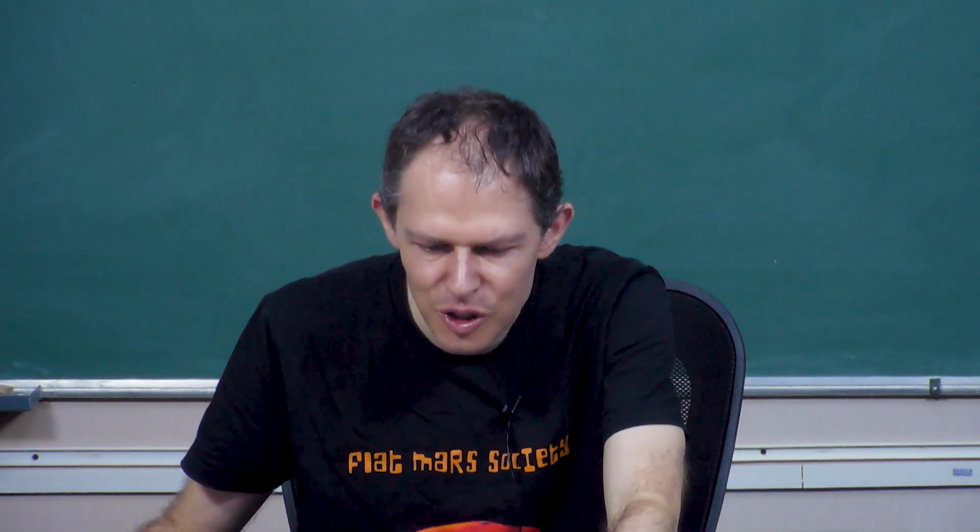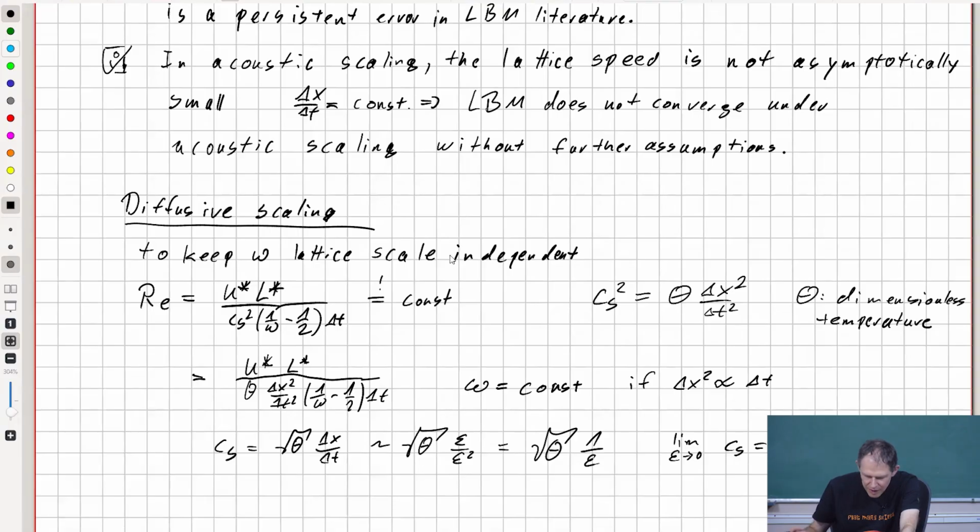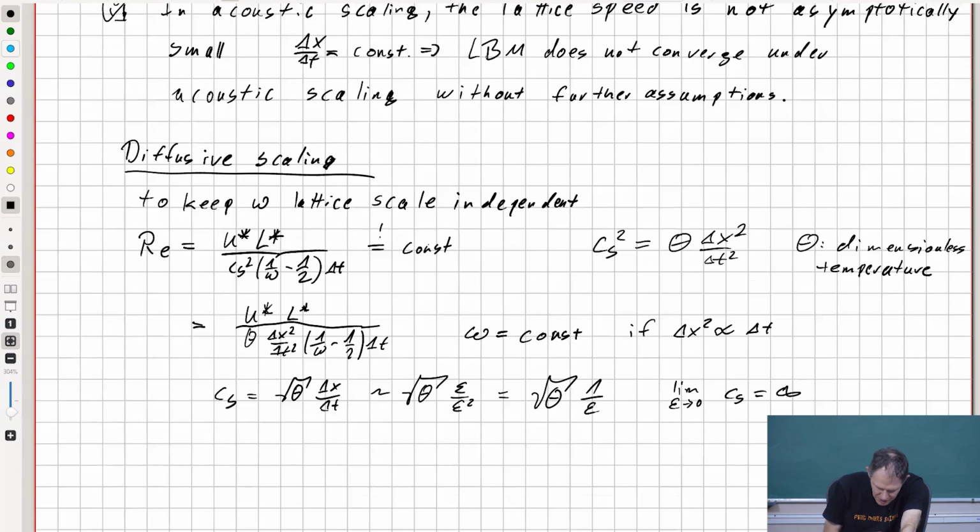So we get convergence. Yes, because the simulated velocity now gets asymptotically small. Now it's true, if we have an error term that is u cubed somewhere in our results, and we refine the grid, then this u cubed error goes asymptotically to 0. It will vanish. For smaller and smaller grid spacing, this error becomes smaller and smaller compared to the solution.